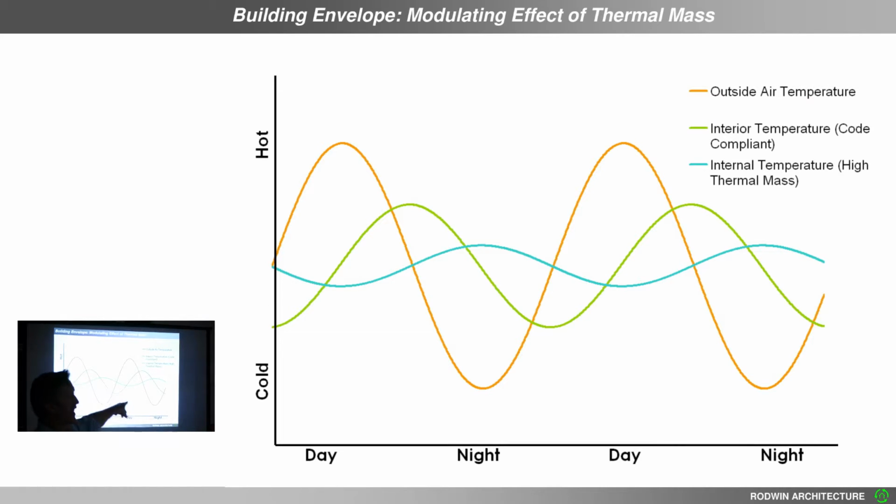This particular strategy of a high thermal mass building actually works particularly well here in Colorado, because it gets cold at night, cools the building down, but the building stays nice and warm for most of the time that it's dark outside, and it reaches its lowest temperature just as the sun is rising. So as the house starts to heat up, you've gained all this natural cooling effect from the cool outdoor air. And the same thing happens during the day, that the house starts to warm up and then it stays warm throughout the night. So that's the thermal coasting or thermal lag.